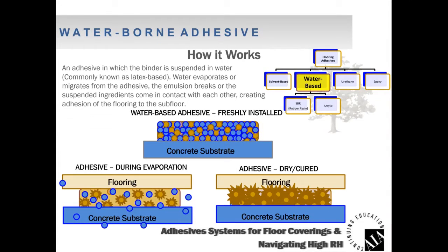Just about all of your adhesives, the majority of your adhesives today, are made with water, hence the term waterborne adhesive. Water's the carrier. Water is getting that acrylic to the floor or the wall. Water's getting that SBR latex to the floor or the wall. Once the water flashes off, then the adhesive can start to coalesce and bond that flooring to the substrate.